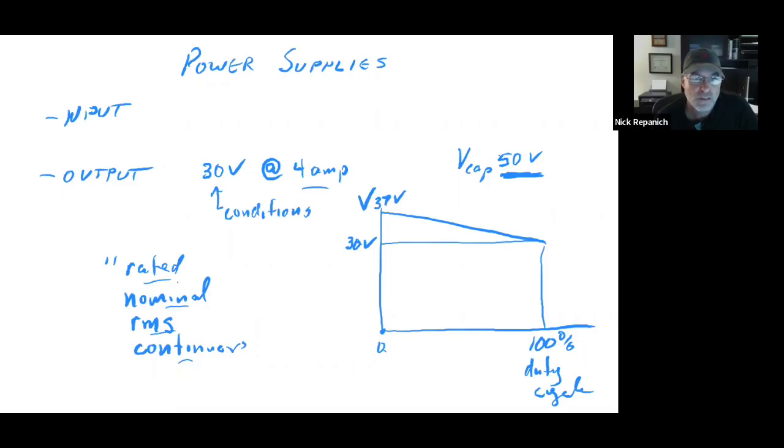Where's it go when it decelerates? Depends. Maybe a little to friction, but that's why it's at 50, not at 30, because it's ready for some amount of energy to come back to the power supply, because that's what it does. It's a generator.